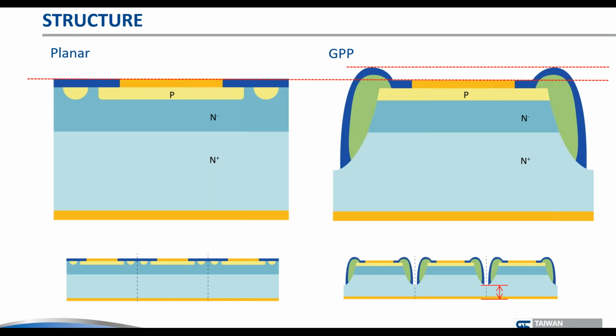And for the rest, of course, you have your PN junction. So the glass stands off a little bit higher than the wafer. That's why you need specific dimple designs, as we call them, or the lead frames need to be adjusted for that. And what you see, if you look carefully here, is that on the bottom side those grooves are very deep into the glass wafers.